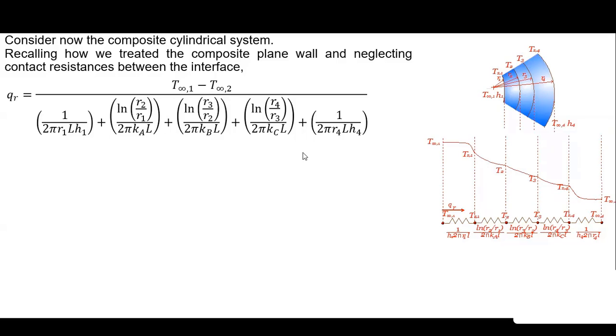Okay, so this is a simplified form of this equation, and it can be used for finding out the heat transfer rate in practice. So, what we need for finding the solution of this problem are the values of R1, R2, R3, the values of the inside and outside temperature along with the heat transfer coefficients, and the thermal conductivity of these respective materials. So with this brief information only, we can simply find out the rate of heat transfer.